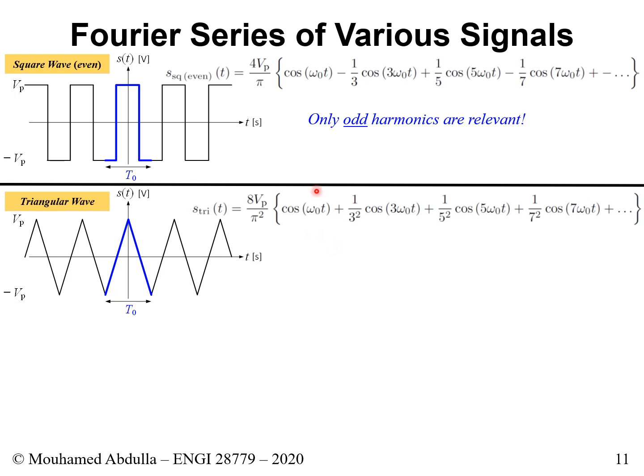Again, we see here, similar to this, we see a bunch of cosines. Is it okay that we're seeing cosine? Well, the answer is yes. It is fine that we're seeing cosines because this is an even function, and with an even function, the Fourier series should have cosines. So that's a good sign. Where is the DC offset?